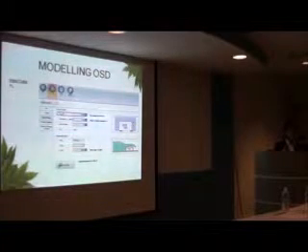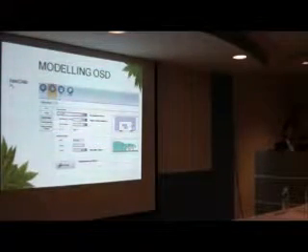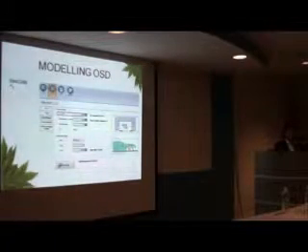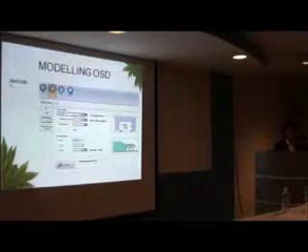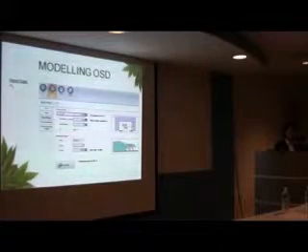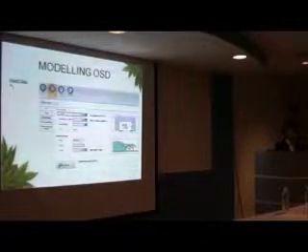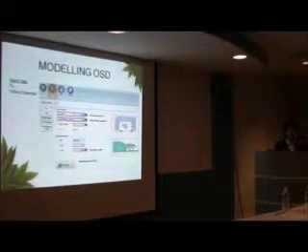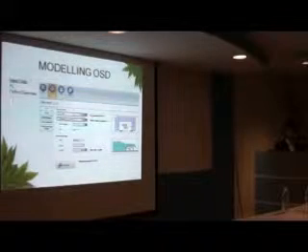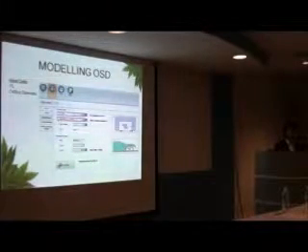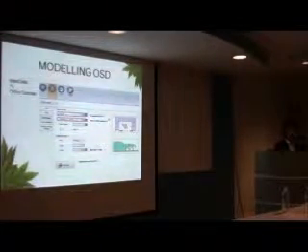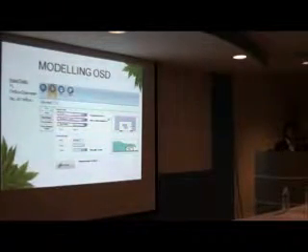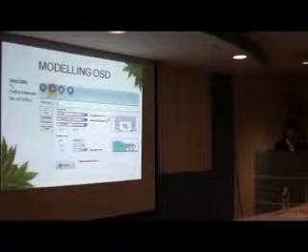Here we need to firstly decide where the orifice will be located. Firstly, we need to know where we want to put the orifice. Normally it's at the very bottom. This is H0. Then the other input we need to give to the program is the orifice diameter. Then the program will do back calculation and recommend how many orifices are needed. Then we can input according to the proposal, or we can input more.